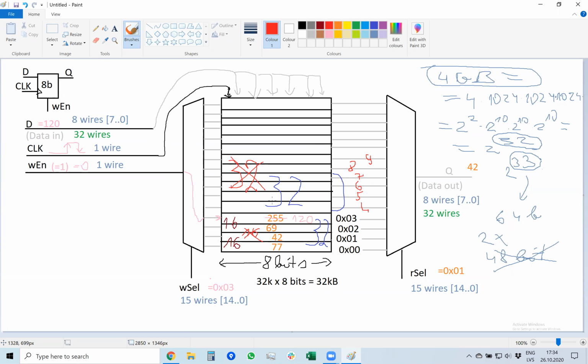So either you personally, if you write it in assembly language, or the compiler, if it is smart, knows it and automatically does this process, but it stores 32-bit variables only in such addresses in which the first location, the bottom part of this 32-bit number, is stored in an address that divides by 4.